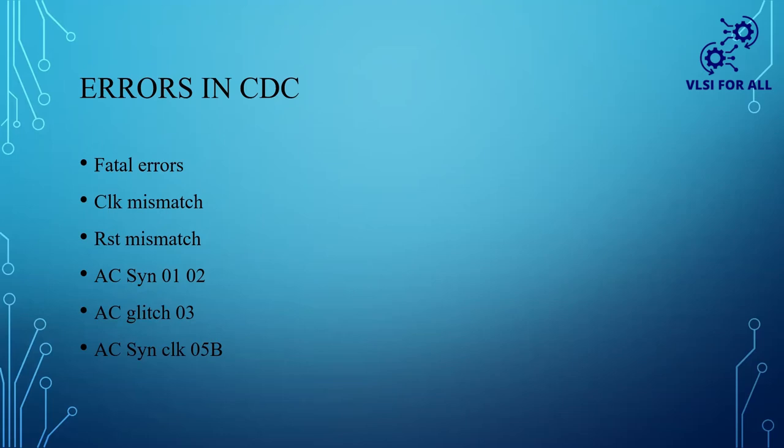The tool doesn't say, see, you are having a comma error, so go and check the comma. It just says you are having some fatal error on a particular line. So we have to understand it. Fatal error means what? Margin, comma, comments, everything comes under fatal error. So on a particular line we have some fatal error, and you should go and delete it. Same with clock mismatch error: on a particular line you have a clock mismatch error, so you have to go through that. Like this, the tool throws errors, and based on that we have to rectify the errors and proceed with the design.